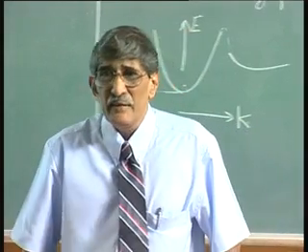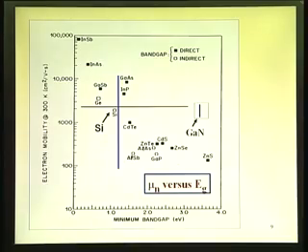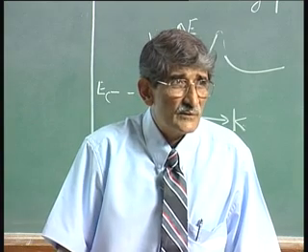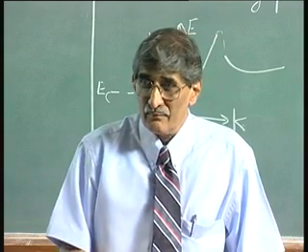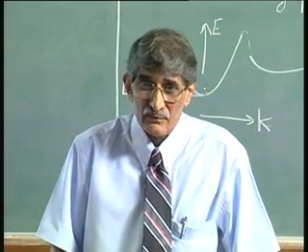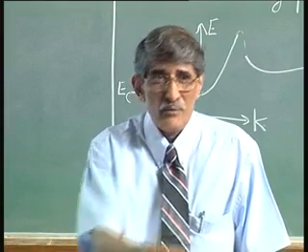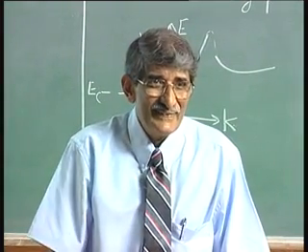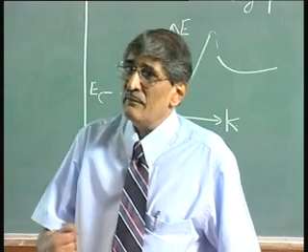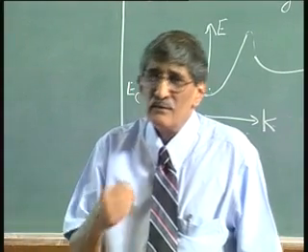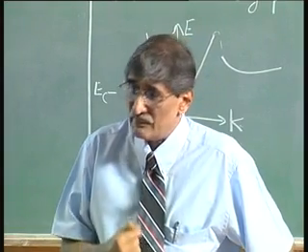If you take, for example, a material like gallium arsenide, its band gap is 1.43. Okay. There, the band gap is higher than that of silicon, which would mean the intrinsic carrier concentration at room temperature is much lower, about 10 to the power 6 per centimeter cube. So, very easily you can do. At the same time, you must be concerned about the impurities that come in also. Impurities in trace of 10 to the power 8 will show up as some sort of a dopant. Whereas silicon, if the impurity is at the level of 10 to the power 8, you won't care about it. So these are some of the classic things which one has to remember, very important things one must remember.